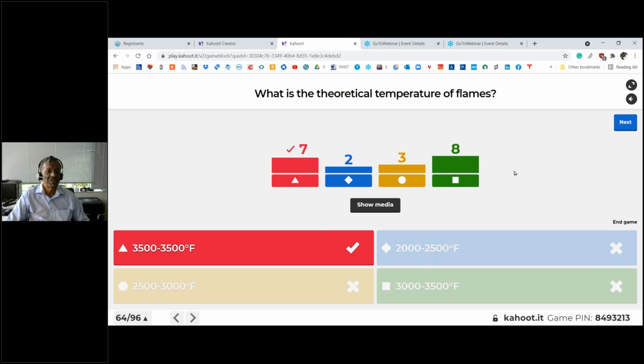And what I want to tell you here is, imagine flame touching your tubes. When we talk of flame impingement, we are talking of flame touching your tubes. And imagine if you have anything at 4,000 degrees F or 3,000 degrees F touching your tube, it is doomed. So that is why flame impingement is one of the biggest problems in our industry. Any heater you take, you will see flame impingement is leading to lots and lots of problems. So we generate these flue gases at about 3,500 to 4,000 degrees F.